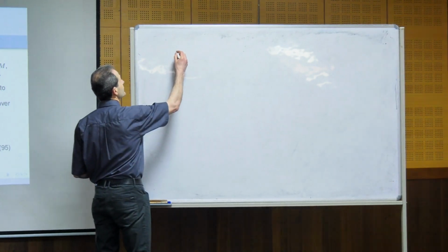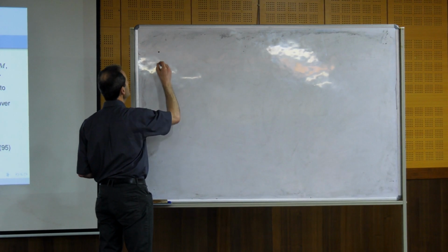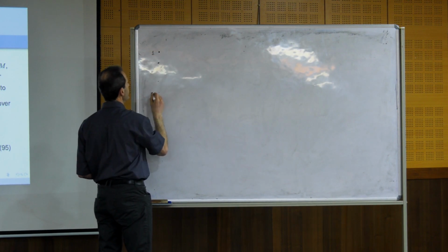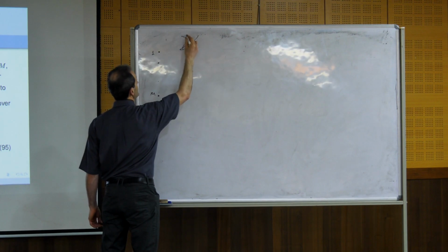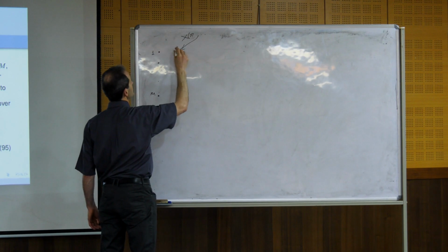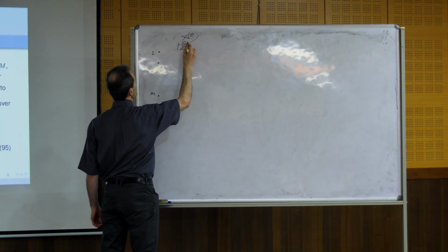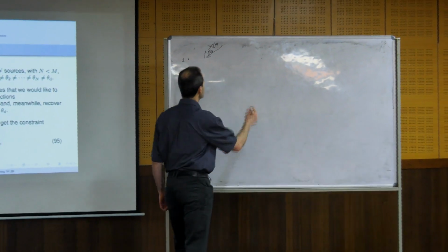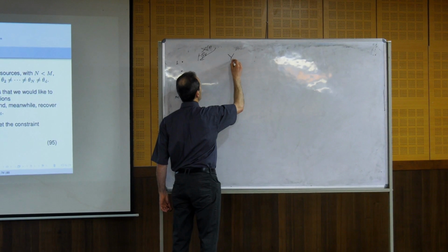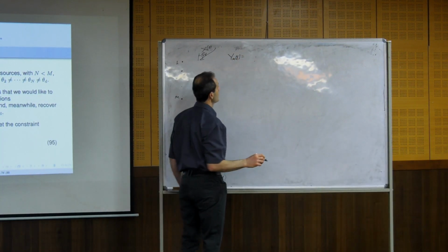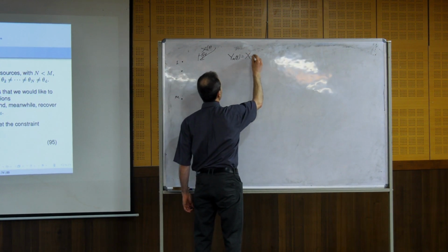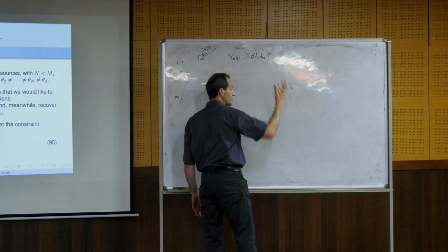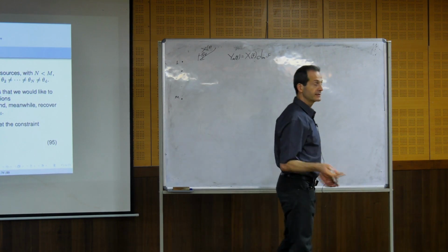So the model was like this. If we have an array of M sensors, numbered 1 until M, and we assume that we have a desired source that comes from a certain direction, theta d, and we assume that we know this direction, we can write our model as Y_m(f) equals X(f) d_m(f), and I can write either cosine theta d or just theta d, whatever you like.